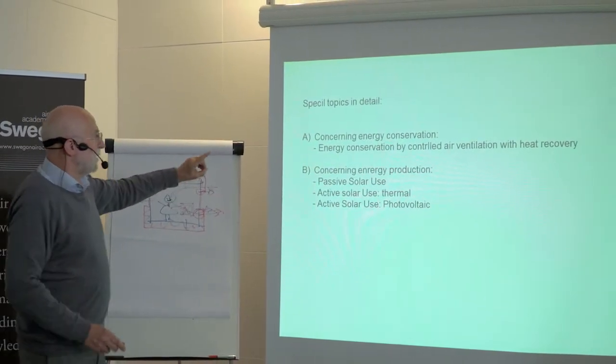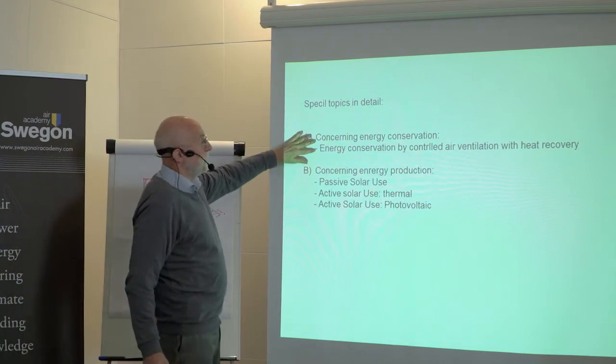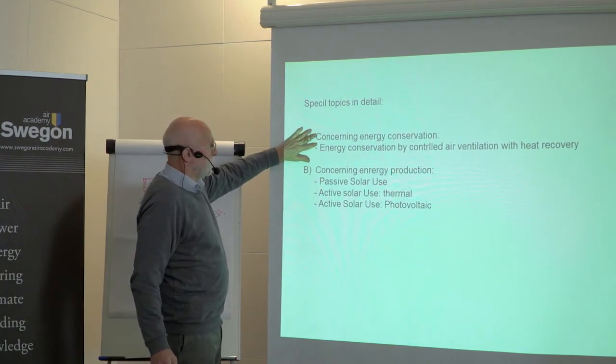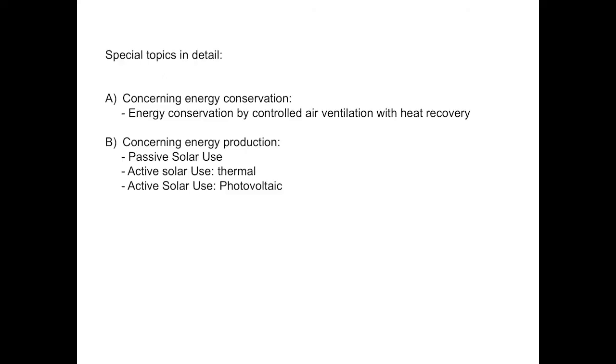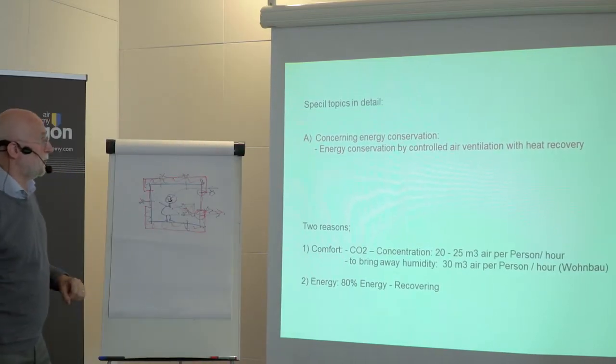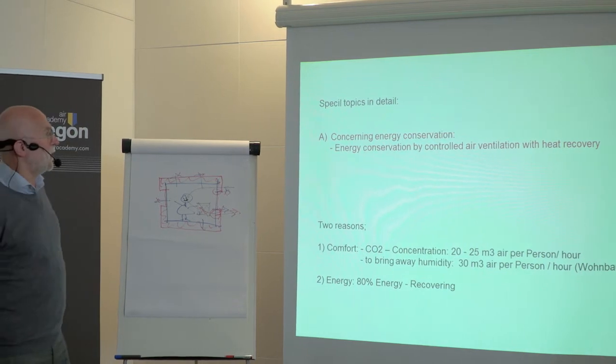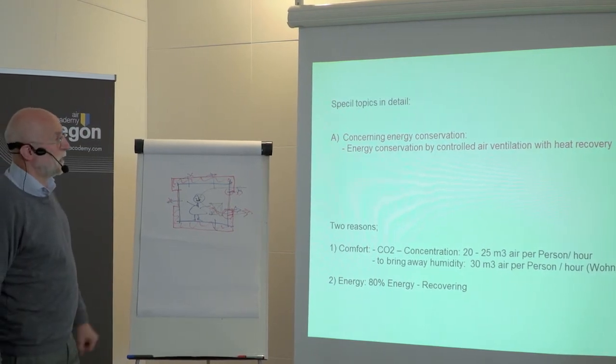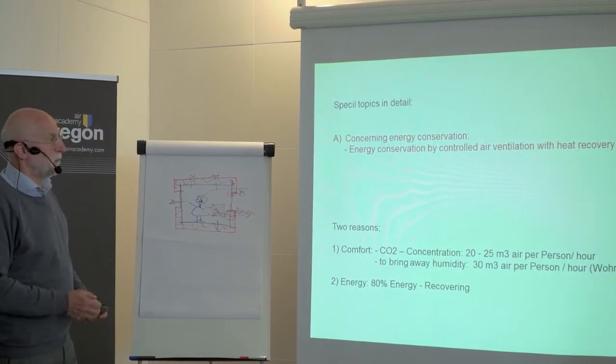I will touch a little bit more in detail concerning energy conservation, the controlled air ventilation, and concerning production, these three solar strategies, because they are very important for me. First, energy conservation by controlled air ventilation with heat recovery.